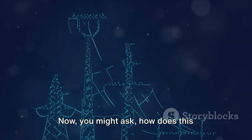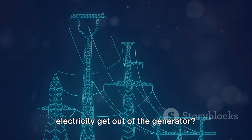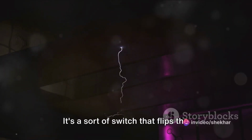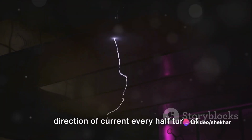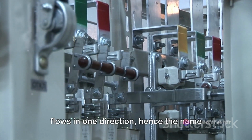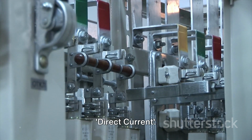Now, you might ask, how does this electricity get out of the generator? That's where the commutator comes in. It's a sort of switch that flips the direction of current every half turn of the armature. This ensures that the current always flows in one direction, hence the name direct current.